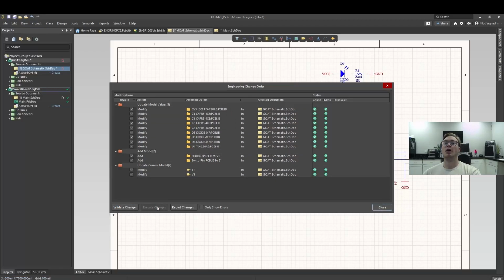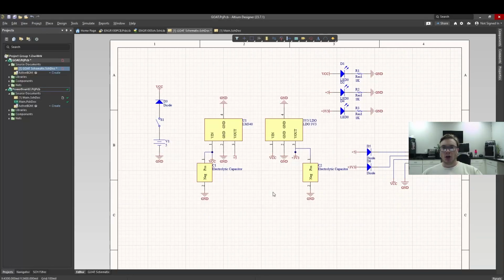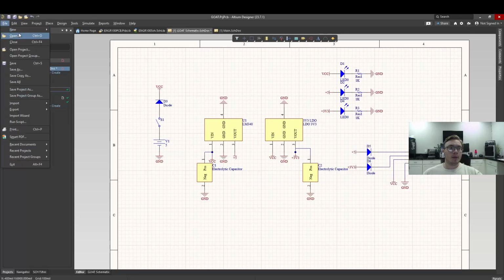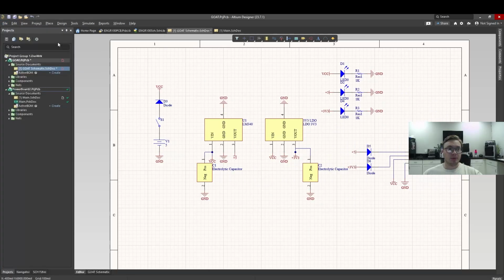Awesome. Now, everything is correct. You can see here all the changes we made, just modified a couple. Hopefully we have these all linked properly when we give you the library. If we don't, I will upload a list of what goes with what, and you can practice this step for yourself. So, now that everything is linked correctly, we can go to File, New, PCB.